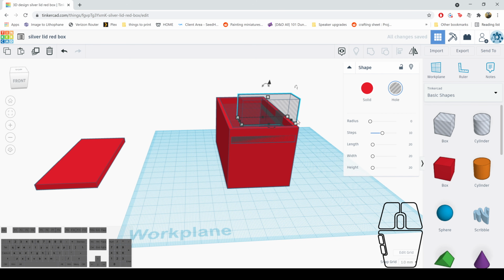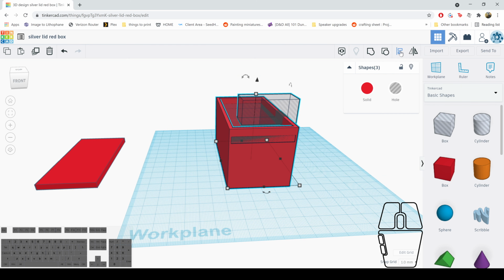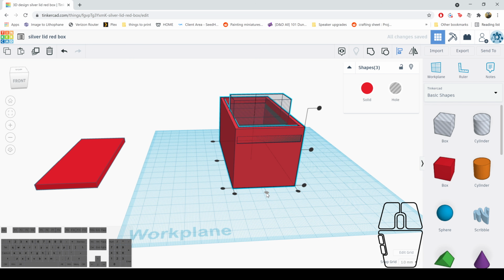and now to select everything in a line. So put the cursor in an empty spot. Let's drag out our selection box, align tool, or L if you want to use the keyboard shortcut. And we're going to give it the exact same alignment as the lid insert, which, as you might remember, is the center dot here, and then up to the front.